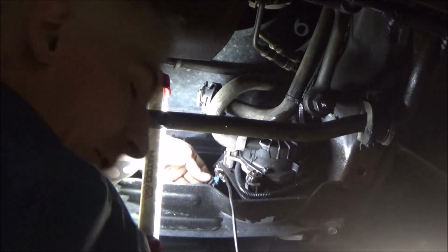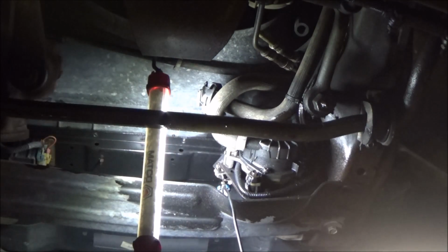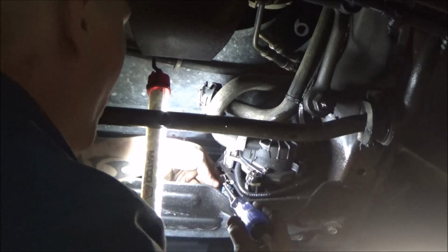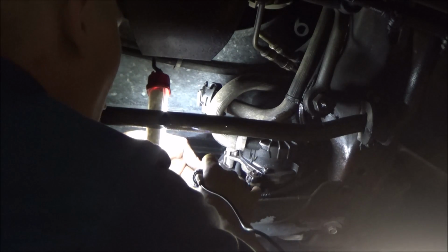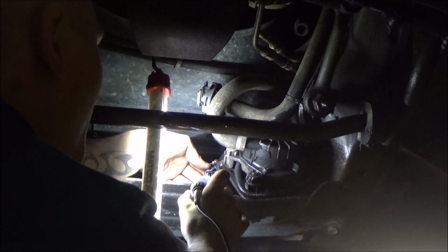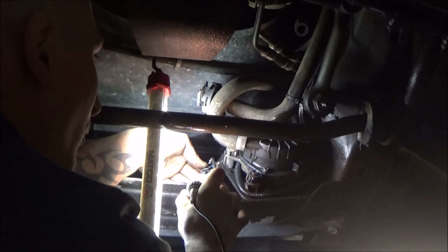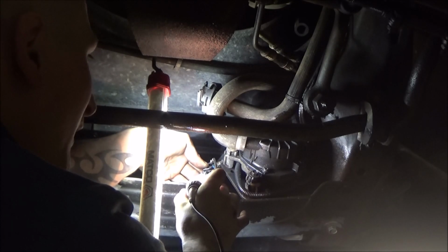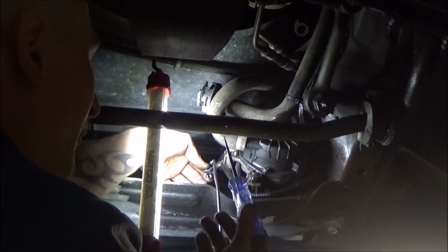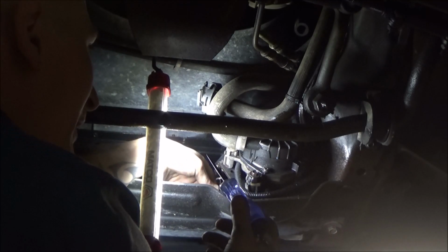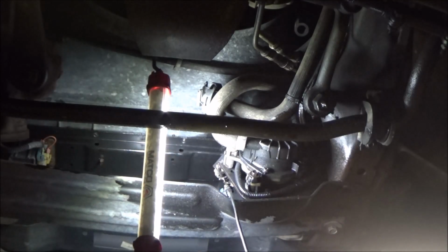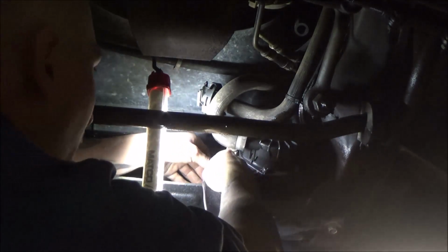So I have the T-pin installed in the ground terminal of this air injection solenoid, and all I'm going to do is turn this air pump relay on, which it currently is, and I'm just going to front probe our power feed terminal on this connector and make sure that my test light lights. And as we can see, it does. I'm making sure my T-pin doesn't touch ground so it doesn't skew our results. And we can see my test light lights. This test light draws 800 milliamps almost on the dot. So that really confirms circuit integrity on this is fine. I'm going to go ahead and remove this T-pin at this point, guys.